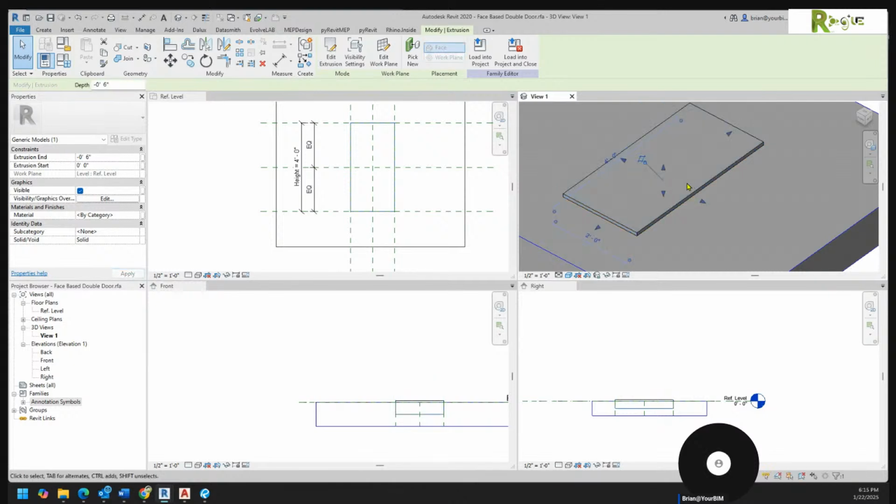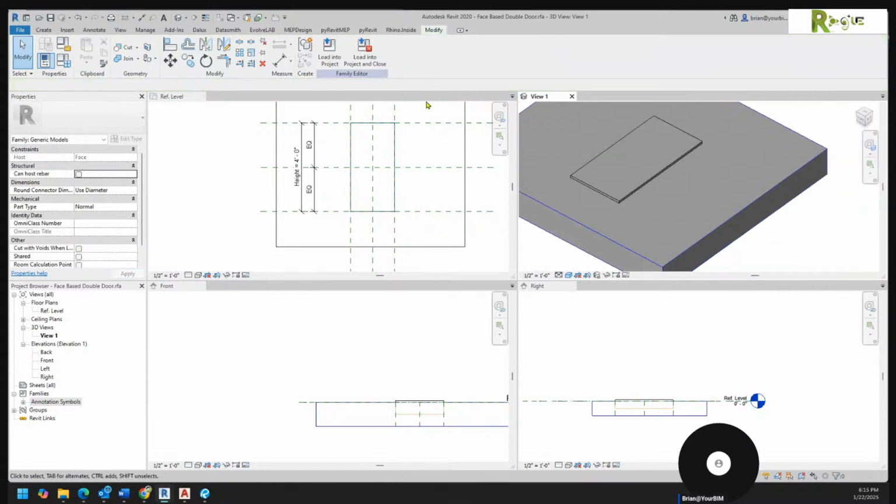All right. Now, you don't really see anything right now, but I'm going to change this guy to a void. And then I'm going to come in here and do a cut. I'm going to pick this object and I'm going to pick that. And watch what happens when I hide this door. I just cut a pocket in there. Okay, so if I unhide that, we're going to start to play some games, because that's what I figured I'd do till 7 o'clock. So that's pretty good for 45 minutes.